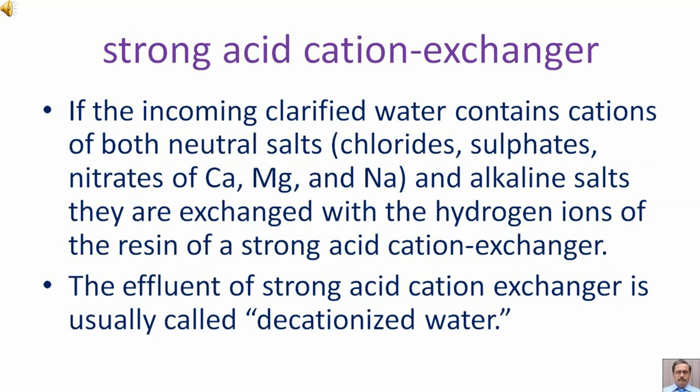If the incoming clarified water contains cations of both neutral salts, that is, chlorides, sulfates, nitrates of calcium, magnesium, and sodium, and alkaline salts, they are exchanged with the hydrogen ions of the resin of a strong acid cation exchanger.